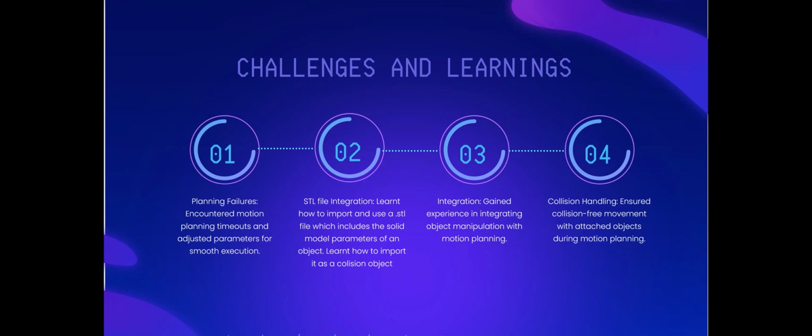The second part was integration of STL files. The STL file is not easily accessible in the MoveIt repository. So I had to actually download and design a small wheel, which I was able to then import into the MoveIt scenario.